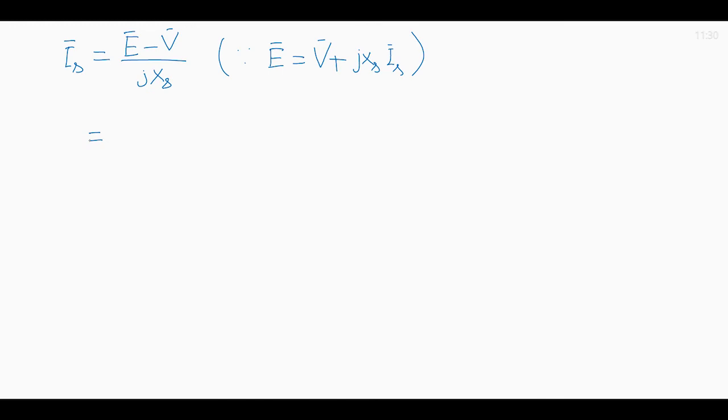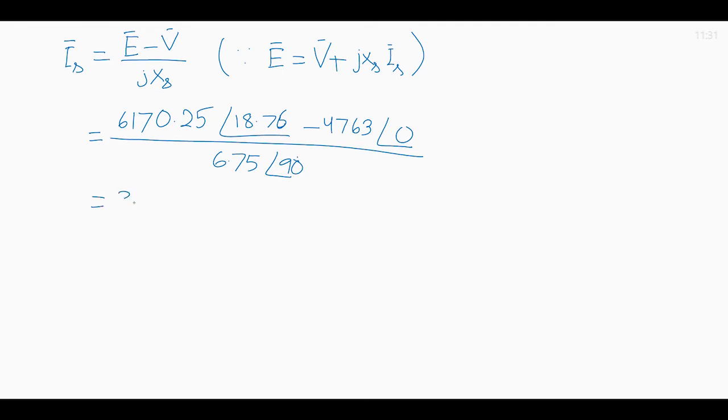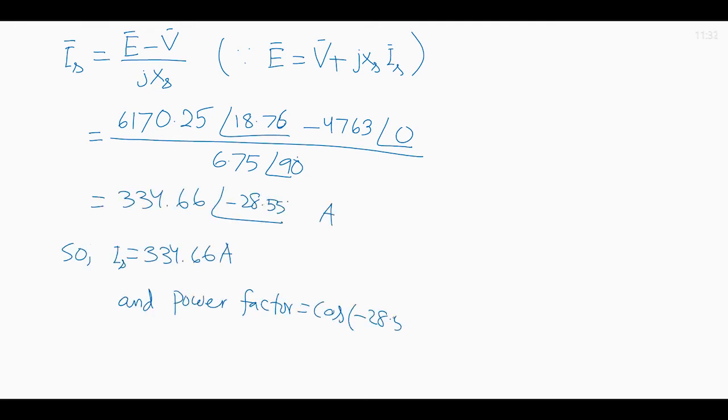So induced EMF magnitude is E1, that is 6170.25. So stator current IS is calculated as 334.66 ampere and its power factor is 0.878 lagging.